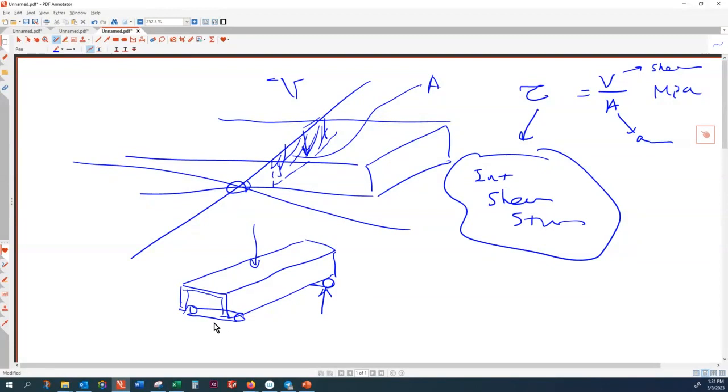So you find the reactions here, and then you have to find out the moment of inertia of this section. You can calculate the amount of the force, and then I ask you to find stresses here and stresses here. So I give you a few points, point 1, point 2, point 3, and then I ask you, can you measure these stresses? So what you do is you find the moment of inertia for the section. All the dimensions of the beam you can measure in the lab, and this is a composite section.